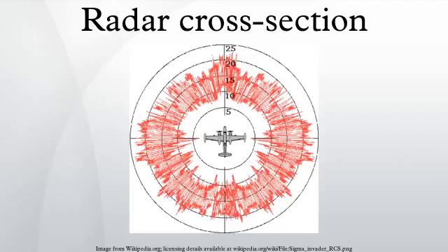In general, RCS is a strong function of the orientation of the radar and target, or, for the bistatic case, a function of the transmitter-target and receiver-target orientations. A target's RCS depends on its size, reflectivity of its surface, and the directivity of the radar reflection caused by the target's geometric shape. Factors that affect RCS.